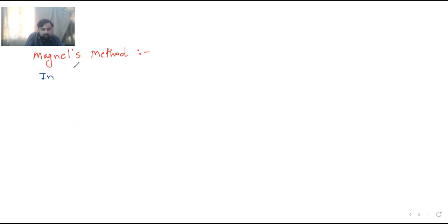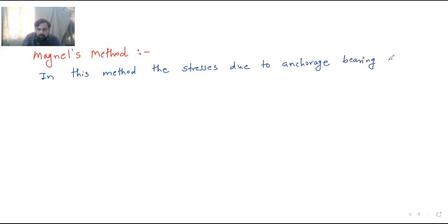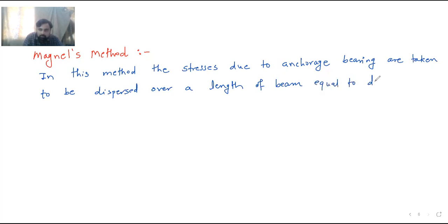Here I will write: in this method, the stresses due to anchorage bearing are taken to be dispersed over a length of beam equal to the depth of beam.